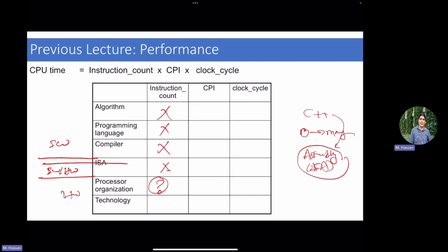When we say technology is 7 nanometer or 9 nanometer, what does it really mean? The size of transistor is a closer answer, but there is a more fine-grained one. When we say the size of transistor, what is exactly this? Because nanometer is not really a unit of size, right? It's a unit of length, right? Yeah. Yes, exactly. So that's basically the width of the transistor gate, right?